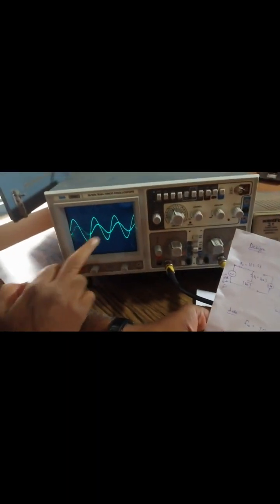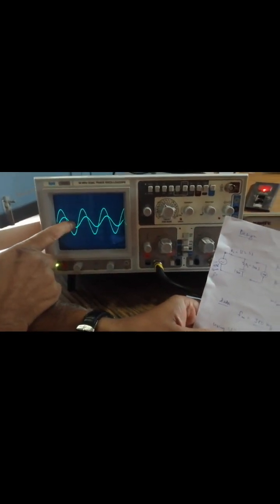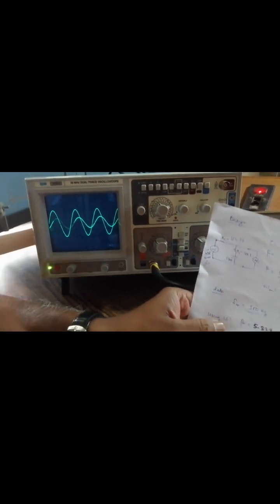The other plot is the phase shift versus omega, the frequency. For that, you cannot measure the phase shift directly from the CRO. Here what you can measure is only the time period. So the time difference between the starting point of the input and the output, I am addressing as delta t. You need to measure delta t, and using this standard equation, which I already explained in the lead compensator circuit, convert this delta t into phase shift. Then using these readings, phase shift versus frequency, you can construct the second plot. So this is going to complete your frequency response.